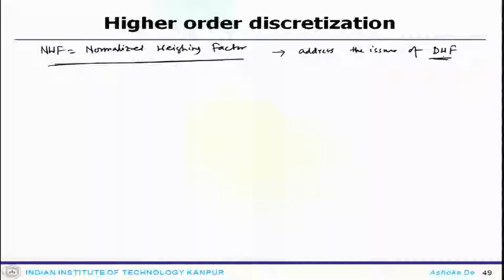It operates by linearizing the normalized interpolation profile such that phi f tilde would look like L phi c tilde plus k. That is a sort of linearization, where L and k are constants.